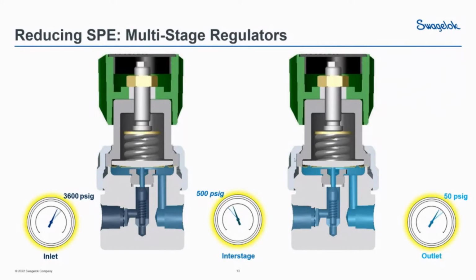We're going to go ahead and draw some flow through the system. And once again, we can see our pressure gauge is moving. Our inlet is dropping. Our interstage pressure is going up, as we would expect. Because the supply pressure effect works on both regulators, the outlet pressure of the second regulator goes down as the interstage pressure goes up.